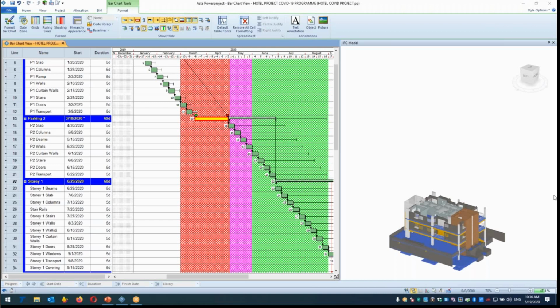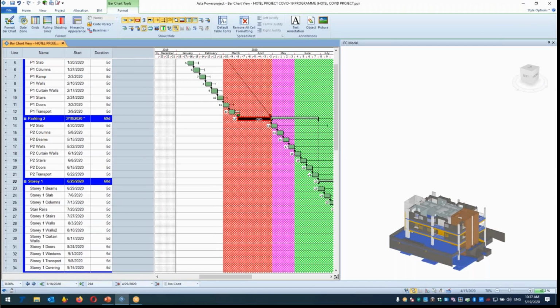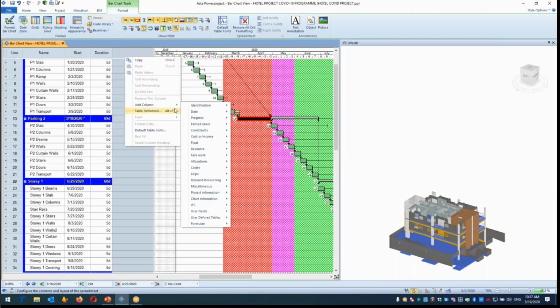Okay, about the cost, are we going to have a cost initiation? Yes, we have a lot of possibilities for the cost. For example, let's just do one simple example, I want to show it. You can model the cost by time, because Powerproject provides cost modeling by fixed cost, time-based cost, and quantity-based cost.